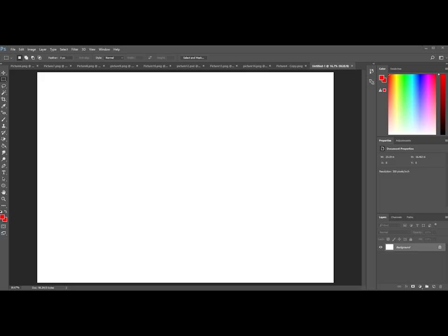Here's how I created a DXF file for the manufacturer. I needed to use Adobe Photoshop and Adobe Illustrator. First, I need to create a canvas the exact size in inches as the desired panel.